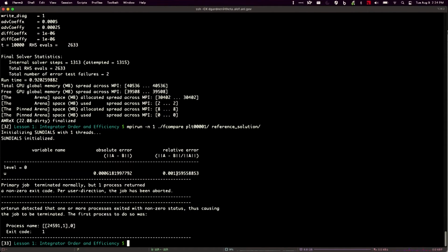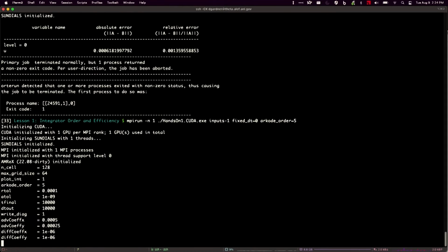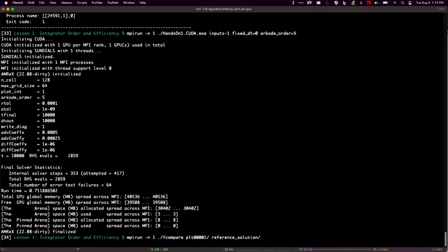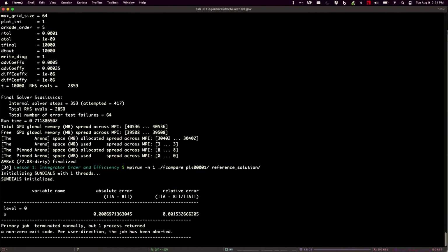We're a little bit undersolved here, right? We're at 10 to the minus 3, but still, pretty good. Try 5th order here and see what it does. Again, it's taking fewer time steps this time, right? Because it's higher order, more accurate, more able to take larger time step sizes, but they cost more, right?